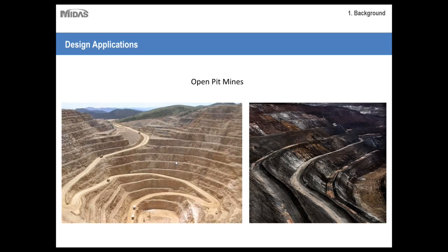Most walls of the pit are generally dug on an angle less than vertical to prevent and minimize damage and danger from rock falls. This depends on how weathered the rocks are and the type of rock, and also how many structural weaknesses occur within the rocks. Because typically these are excavated along rock layers, there isn't too much need for structural supports.